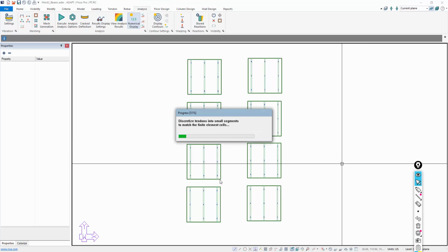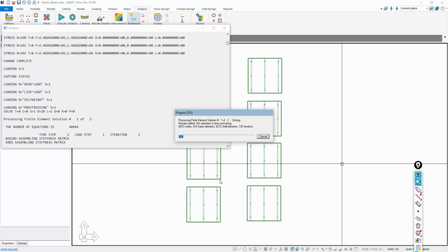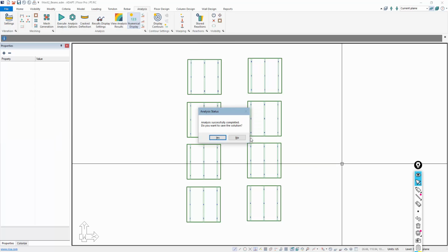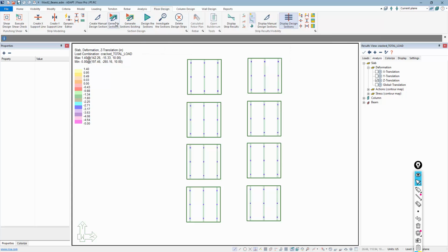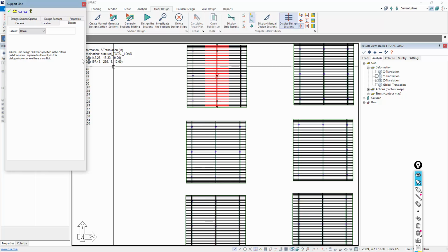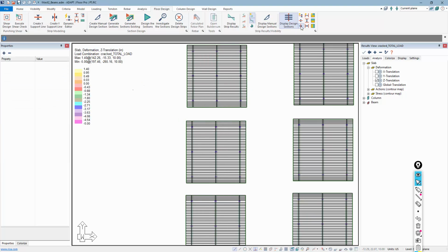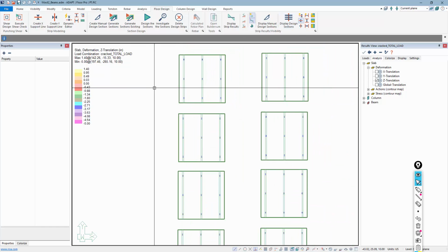In this model, we do use the same identical load combinations and load cases. So everything really is identical other than the actual structural configuration and what's modeled. Again, we're going to generate the design cuts. Now in this case, instead of having two-way slabs, these are now defined as beams in the Y direction, and in the X direction we have one-way slabs.